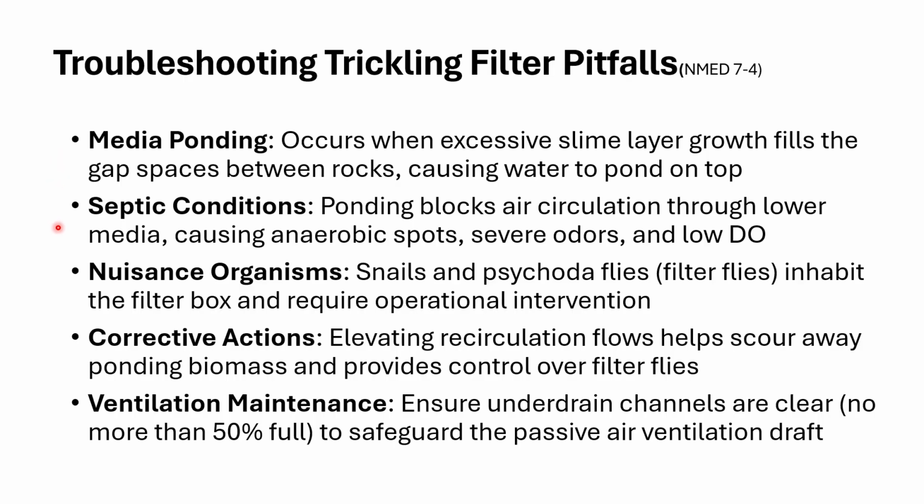Okay, and that ponding, what that ponding can do, it's going to block that air circulation. You remember I told you earlier on, we want those voids present because it's going to allow airflow to go through and allow our microbes to get aerated and chomp away at those wastes. We want an aerobic or oxygen rich environment.